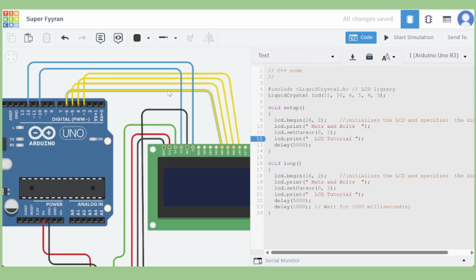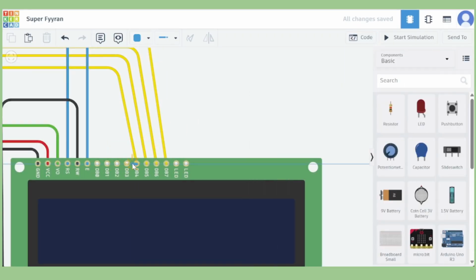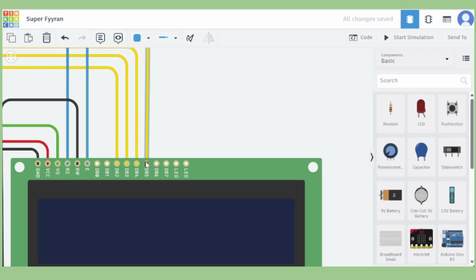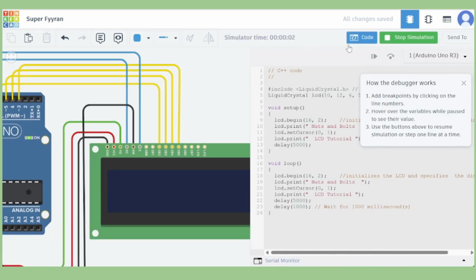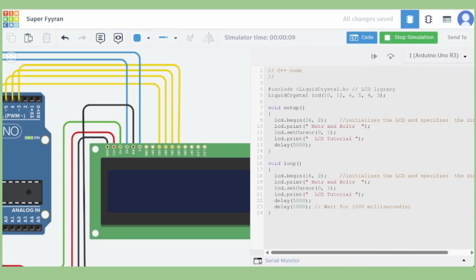The code compiled without any issues. Then I finally discovered I had swapped RS and E in the wiring. After correcting that, the screen finally displayed properly. I still wanted to test whether changing the LCD's data pins would work. After switching to pins different from those listed in the constructor, as expected, it didn't work. The LCD's pins must match the definitions in the constructor.